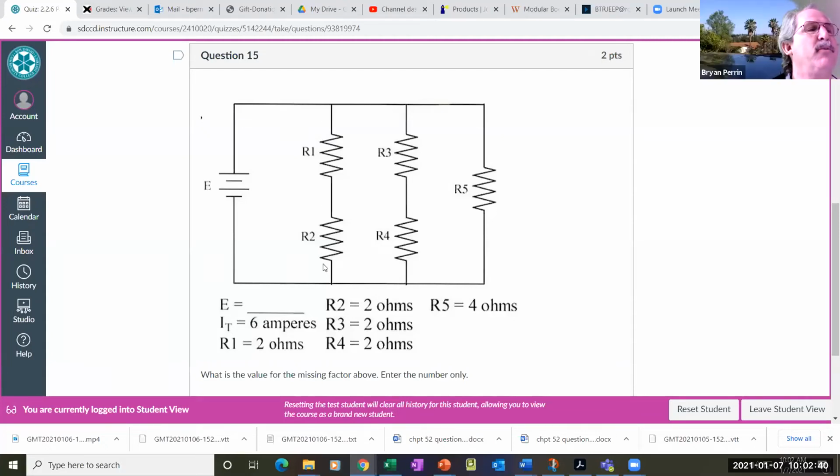It does, because we can do that because each of these legs is its own series circuit. And we know from the series circuit rules that resistance adds in a series circuit. So we're comparing each of the legs. I have 3 legs, all have 4 ohms, 4 divided by 3, 4/3 or 1.333. So that's very convenient because they're equal. You get the 8.